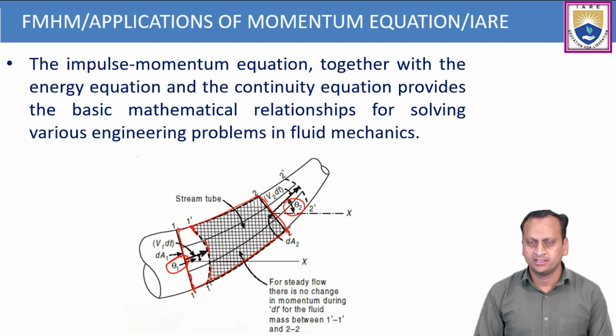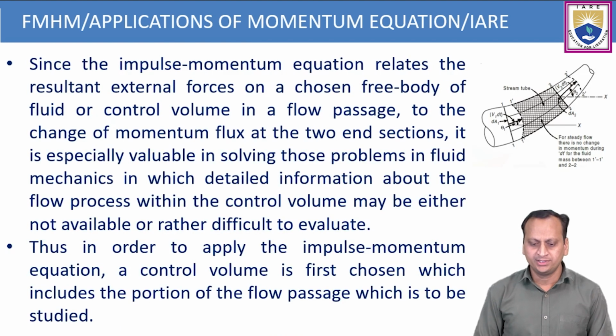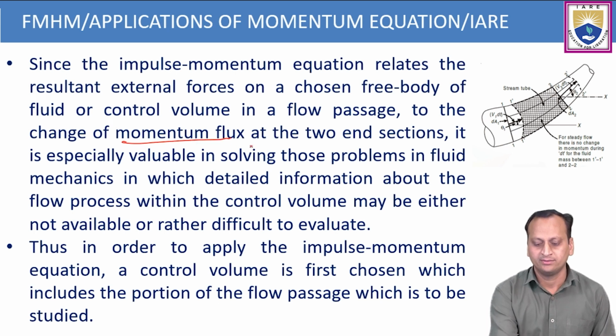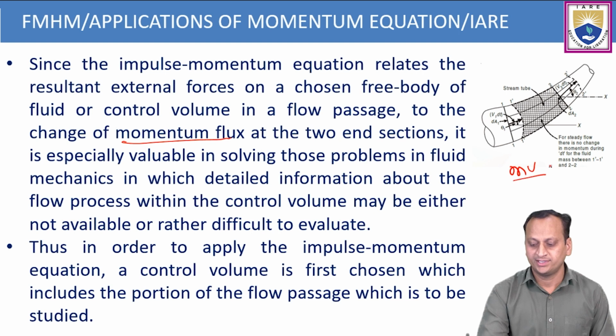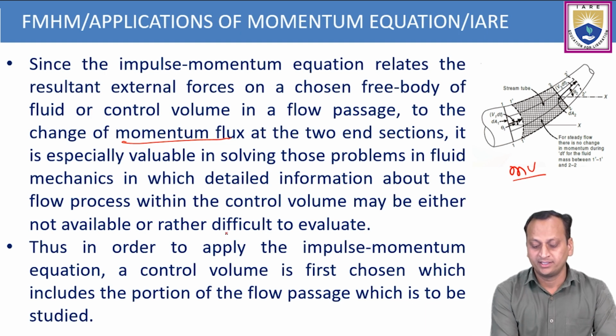You can also calculate the angle through which the flow is taking place. These are some of the applications, since the impulse momentum equation relates the resultant external forces on a chosen free body of a fluid, or control volume in a flow passage, to the change of momentum flux, where momentum flux is nothing but mass times velocity, at the two ends. It is especially valuable in solving those problems in fluid mechanics in which detailed information about the flow process within the control volume is either not available or rather difficult to evaluate.